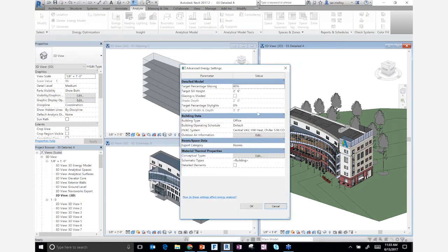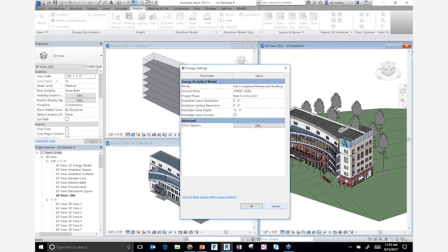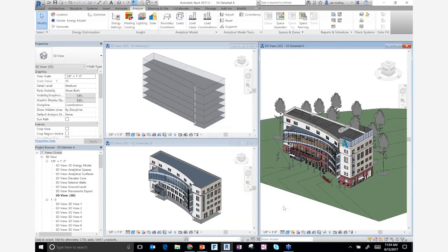Which you'll find here, okay? So you'll see their building type. And the reason we say that's required for the 2030 challenge is that that's relative to a certain building type. The benchmark, which I'll show you later on, is relative to a certain building type. If you're just wanting to explore Insight, it's actually not necessary for you to set the building type because you can actually represent different building types in Insight itself. But for the benchmark to be right, you want to set that building type.